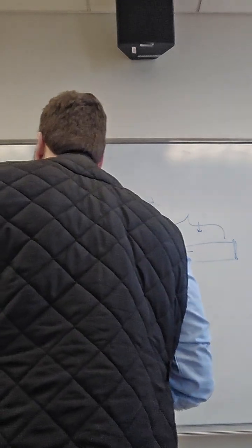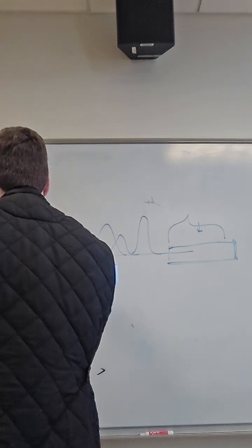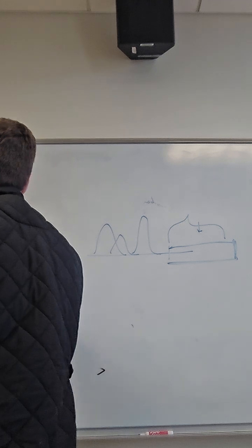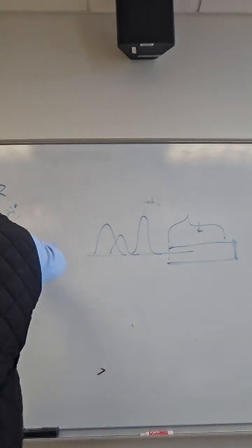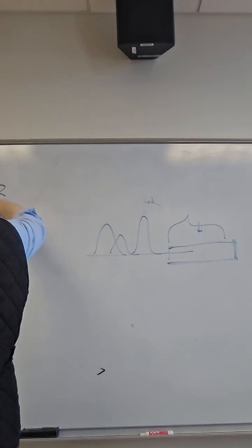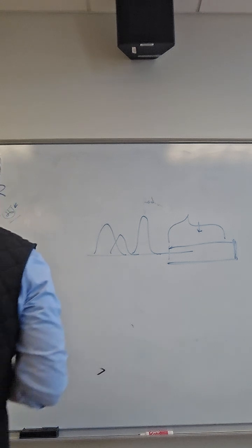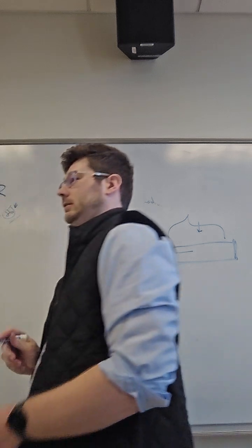Another example adds an emitter. Okay, so PIR relies on ambient IR, things that are emitting IR, mainly people and animals, right? But active IR would swap one or more of these IR receivers for an IR emitter. Okay, so now we have an LED in here that we are sending out photons actively.